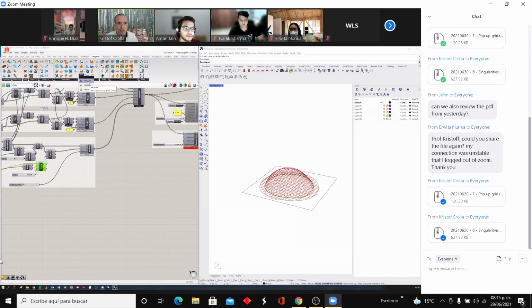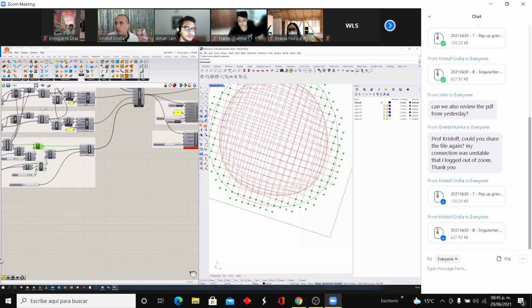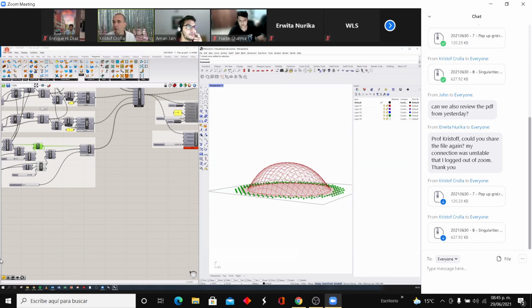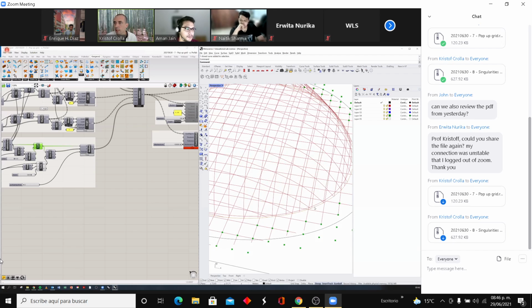But you'll need to be careful, because we're basically pulling all of these points and they're not on a line either. So if you make that one too tight, you're basically going to crush your grid in that area onto a curve, and that doesn't work. So you need to be careful with that. What I've done in the past is do a few iterations. First you do the one that I have here, which is approximate. Then you bake that one, or you internalize the data with the structure, and then you run it again through Kangaroo. And that time you do it with very hard anchors. So you run it a few times and use the first time to get your approximation of where you need to trim your grid, and then your second time to tighten it up. That's also possible as a strategy.